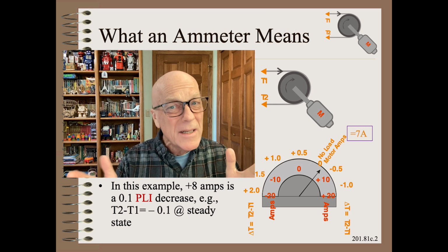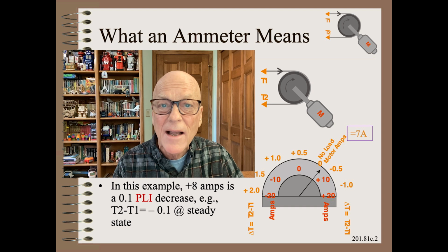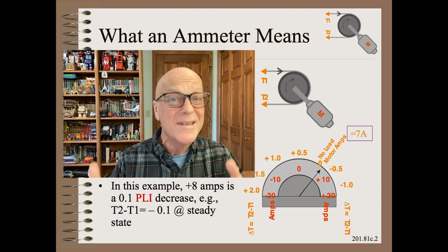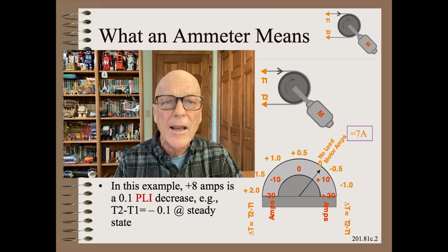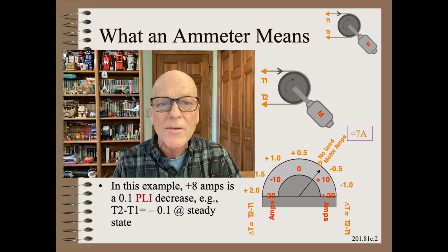However, this is a bit confusing to the layman because 0 amps is not zero effect on the web, meaning also that turning off the motor still leaves an effect. Also confusing to the layman is that more motor torque means less web tension after the motor.